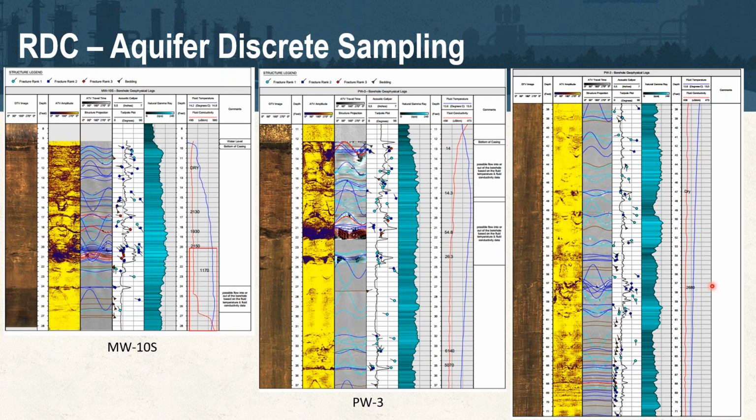And looking back at the far left-hand side, at MW10S, looking at the distribution and effectiveness of that potassium permanganate, again, we're only 10 feet from this particular well, but definitely in the same flow path as where the material is injected and pulled to. We can see that even at that high K zone that's identified in this borehole as well, we still have elevated mass present that's an order of magnitude higher than what we're seeing in the well next to it.